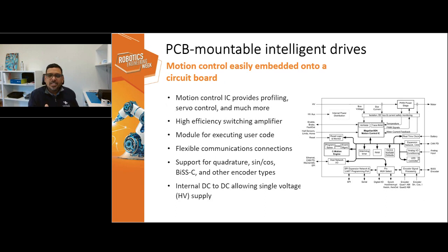This is a deeper dive into the internals of this drive. It has a host processor where you can write C code and download it to the host on the drive. The central controller can then send really high-level commands, saying high-level motion of axes. You can download the feed-forward compensation tables for each axis specific to its own host controller, so it can do all the compensations local to the axes. It has our Magellan motion control IC in there, and then the power amplifier design.